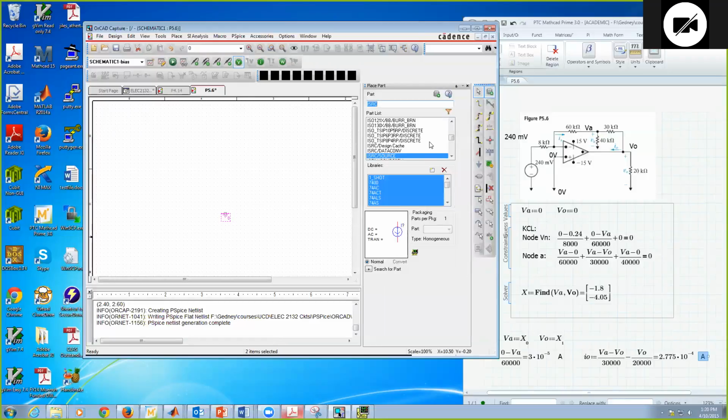What we're going to do is use Orcad's representation of an ideal op-amp. It actually is not specifically ideal. It's an analog device. So I'm going to type in op-amp. It has a circuit model for it, which really is invisible to us. But internal to this op-amp actually is a plus or minus 15 volt rail voltage. So that plays in well, but we know that going in. So I'm going to put in an op-amp.